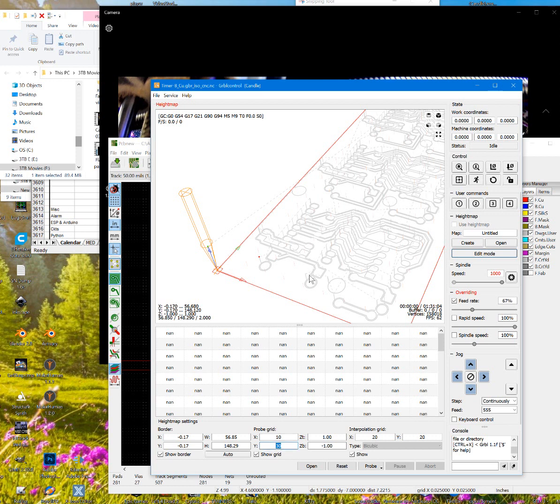But still, I don't want to risk it, because this is such a high density board that, normally I just do like an 8x8 or something like that, but for a board this size, you certainly want to make it bigger, and I just don't want to take any chances given how elaborate this is. It's a lot of work to mess up. So that's why I'm trying to use more points than normal. Normally I might use 8 points across for a 2-inch wide board, and then about 8 points for every 2 inches vertical. So there's 4 points per inch, so it still ended up being about 24. But here I'm going to go ahead and leave it at 30.